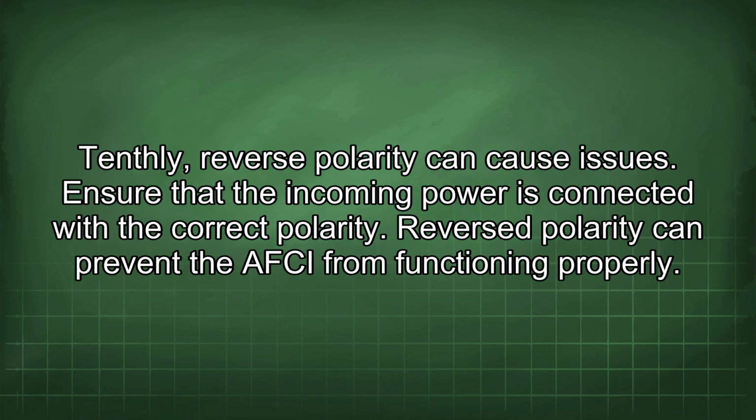Tenthly, reverse polarity can cause issues. Ensure that the incoming power is connected with the correct polarity. Reverse polarity can prevent the AFCI from functioning properly.